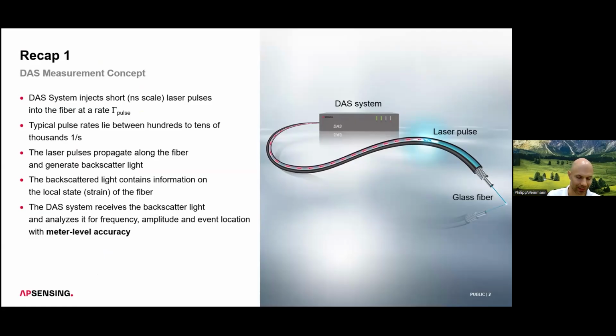We said that DAS works by connecting a DAS system to a glass fiber and thereby transforming the glass fiber into a microphone. That means we will be able to listen to acoustic waves that are impinging on the glass fiber. The DAS system inserts short laser pulses into the glass fiber.